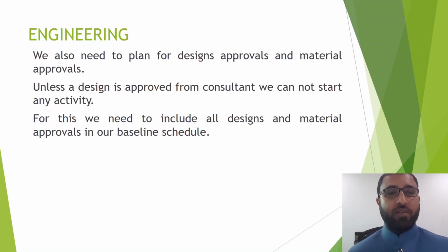Then the third one is engineering. I had already told you that we need to include all the design information in our baseline schedule: what we are going to build, how we are going to build. We also need to plan for design approvals and material approvals. Unless a design is approved by the consultant, we cannot start any activity. So that particular drawing has to be connected with the start of the construction activity. Those submittals and approvals should be activities, and their durations and interconnecting logic should be connected with the activities.